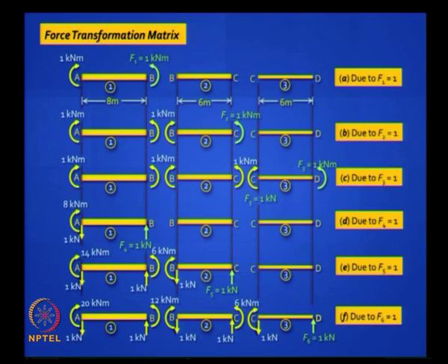We are doing actually the same work because in the force transformation matrix you are capturing the 2 end moments and you are assuming a linear variation between them. So you are capturing the same essence in a matrix formulation. So it is easy to calculate, you will get all this. So you will find the unit load bending moment diagrams will either be linearly varying or will be constant.